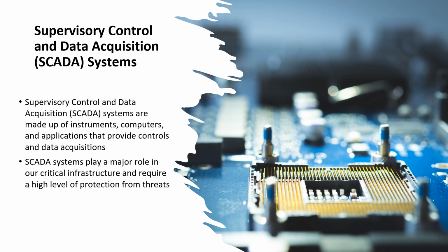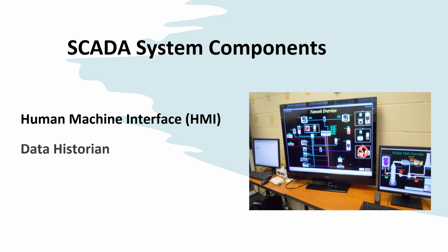The interdependence of critical infrastructures has been investigated intensely and identified SCADA communications as a common link between these systems. SCADA systems collect data and perform centralized monitoring and control. An HMI is the interface between the operator and the SCADA system. It provides graphical and textual displays that facilitate the control and the operation of the system. Further, the HMI provides the operator critical alerts and insights depicting the status of the system.